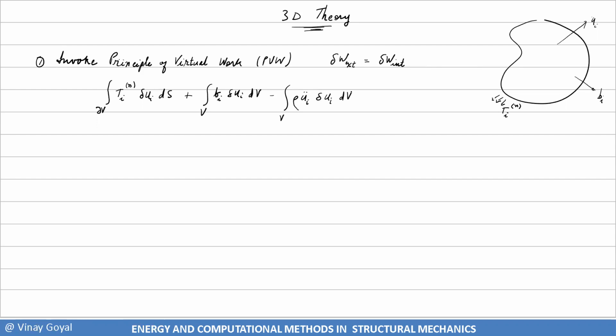And we already demonstrated that the principle of virtual work clearly states that this is equal to the internal virtual work, which is the integral over the volume of the Cauchy stress tensor sigma ij, which acts on the deformed body, times the virtual infinitesimal strain on the deformed body. And again, this works for finite deformation. After you get to this step, what you want to do is substitute what epsilon ij is. That's your next step.